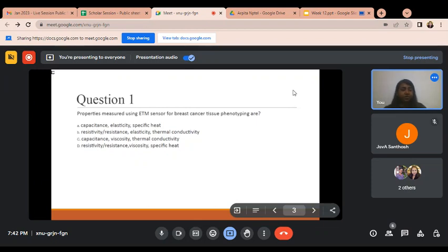Okay, so what happens next, after etching we will dip the wafer into the IPA or acetone. The IPA or acetone will remove the remaining photoresist, some portion of which is present after the developing process. So this remaining photoresist is gone. So now it is clear to you, Santosh?